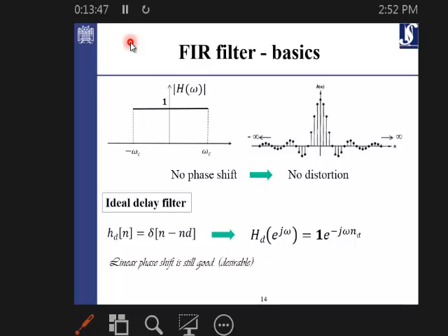As we explained already, the low pass filter like this, which is a rectangular window, and for the real applications we normally have a symmetry. So this low pass filter, here you have a low pass filter with a cutoff frequency of omega c, corresponds to a sinc function in time. So in time, that's a sinc function. If you don't do any phase shift, so there is no phase shift, just like this, you have the sinc function and that's all.